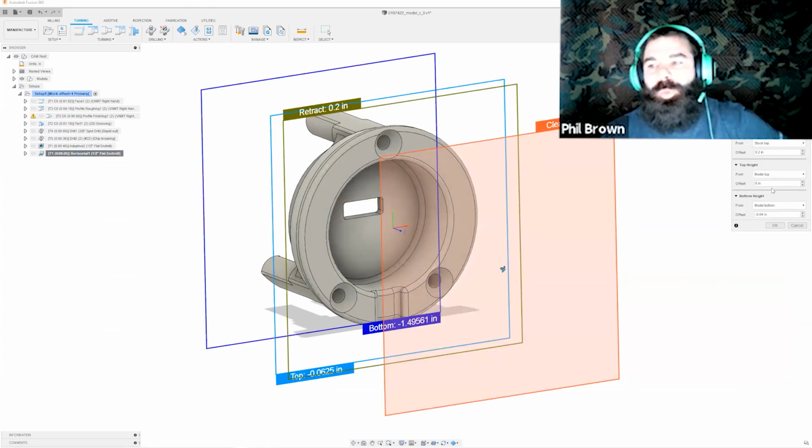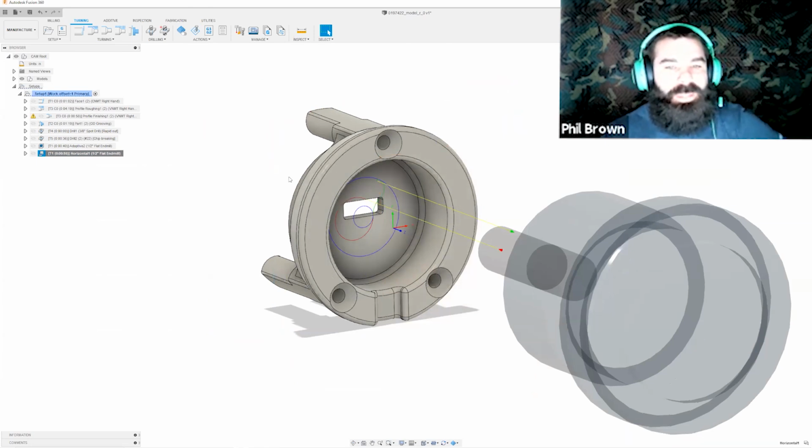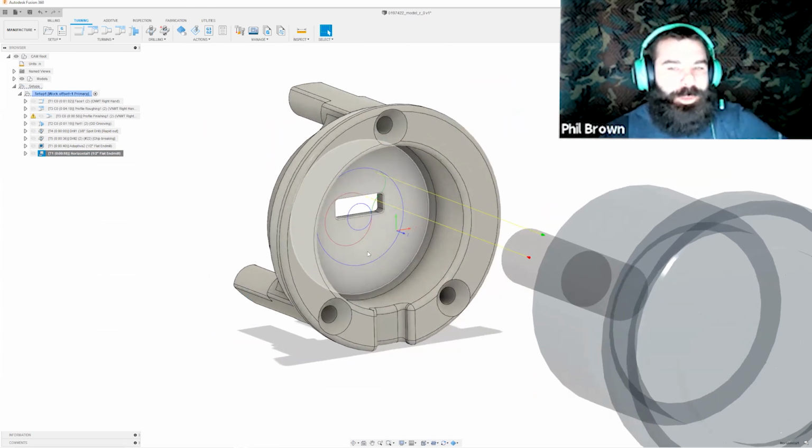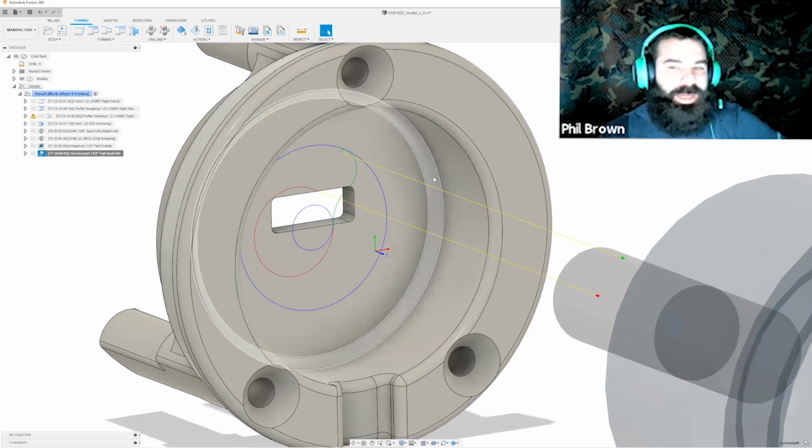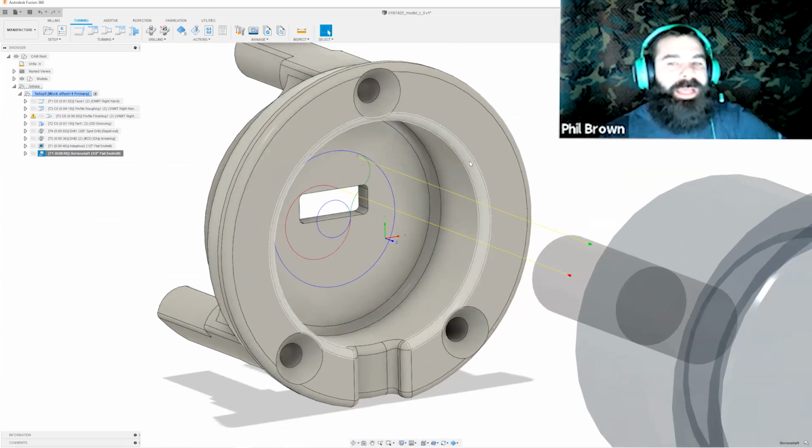The horizontal tool path is great for being able to go in and clean up any flat areas inside of the part. Again, we now cleaned up the floors here. Lastly, I want to go back and machine this wall and this radius and add it into the feature, as well as possibly machining this fillet here. I could, yes, bore this out with a tool by all means.